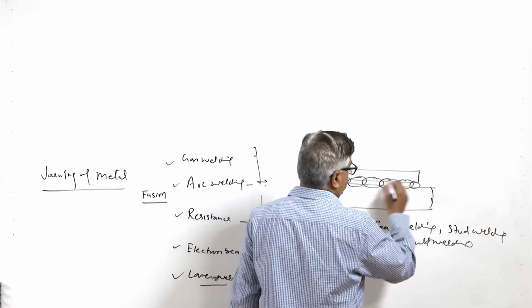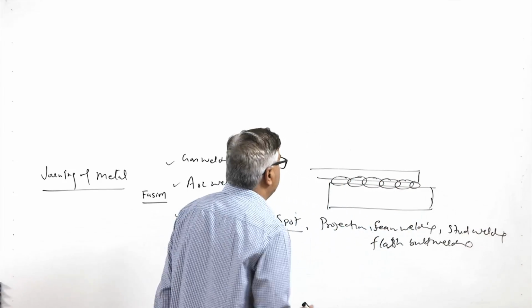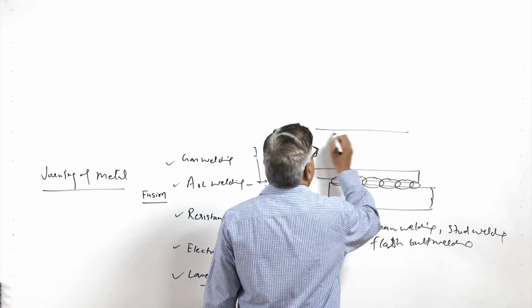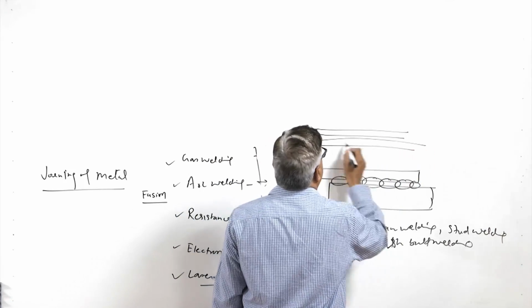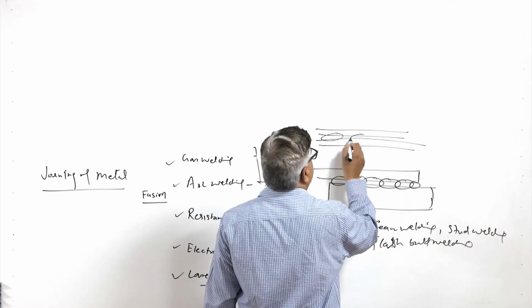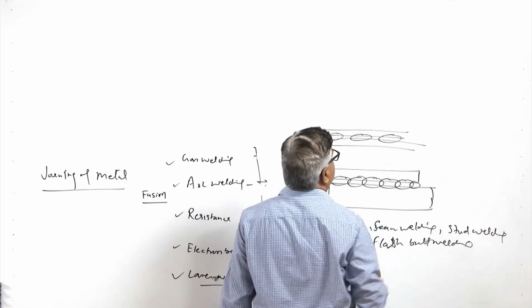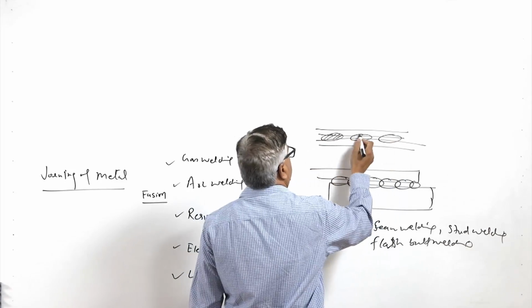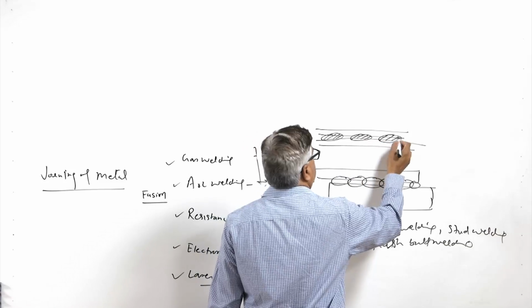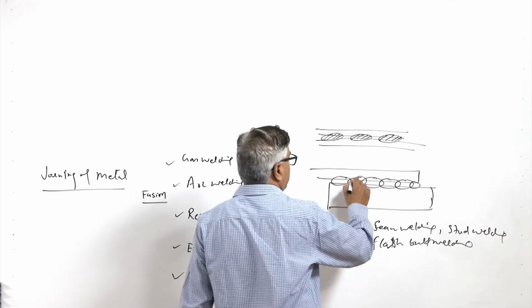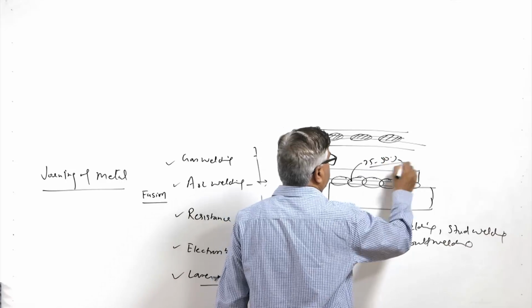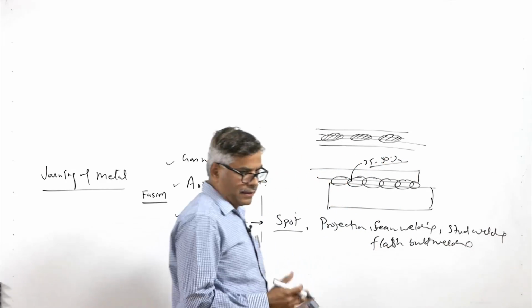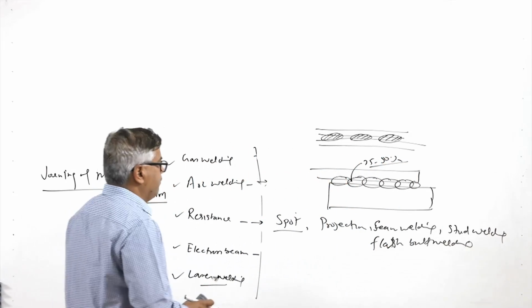Continuous seam or interrupted seam, interrupted spots, are also made when somewhat better strength but not air tightness is needed. In that case spots are made at some distance, otherwise an overlap of 25 to 50% can be used if airtight and leak tight joints are to be made.